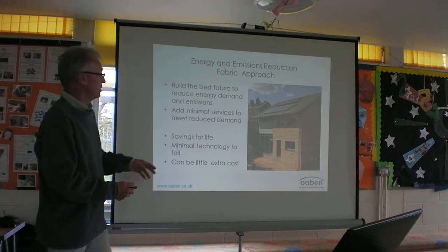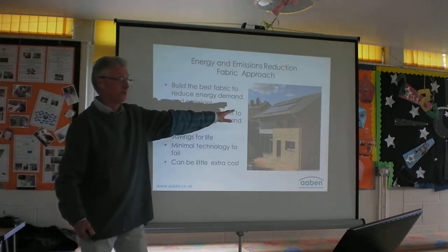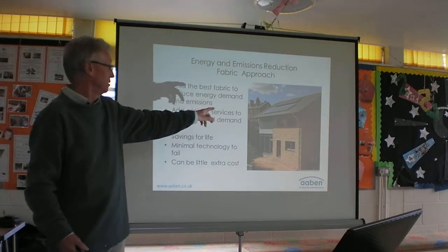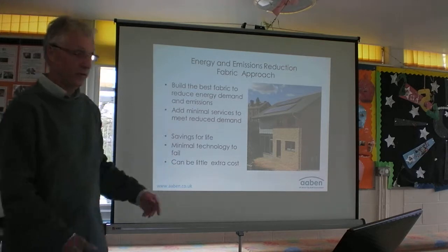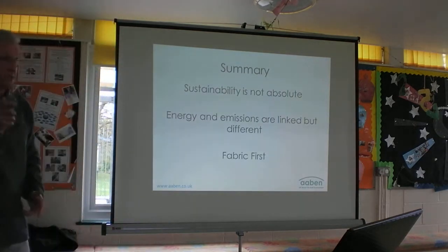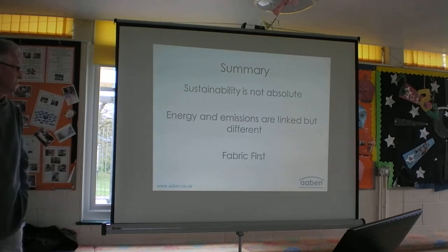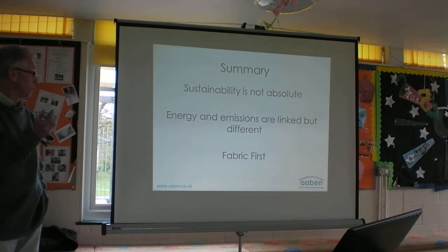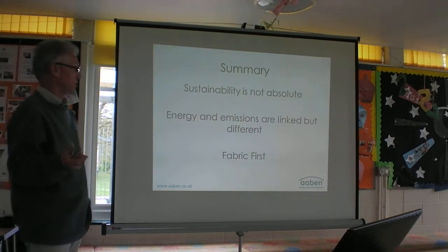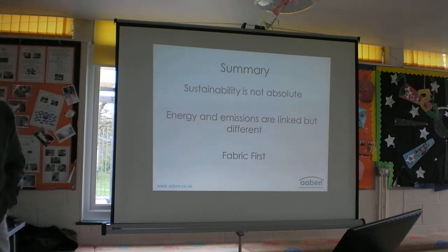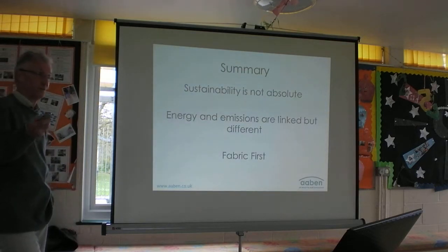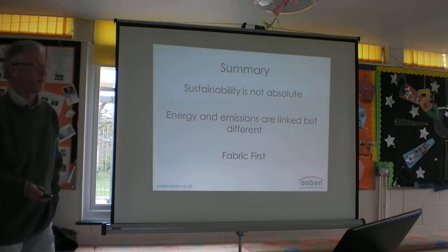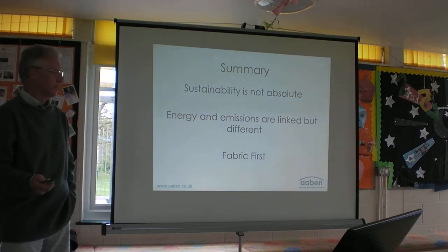Now, the PV on that is probably a retrofit because they were going to get lots of money off the government for putting it on. The solar thermal probably was part of the original design. But that house doesn't need that PV to be very low emissions. So, sustainability is not absolute. It's what you decide it is within the parameters that you draw. Energy and emissions are linked, but they're not the same thing. And I would suggest everybody in green building, most people in building, would suggest fabric first. Because if you build fabric first, you're actually reducing demand permanently.